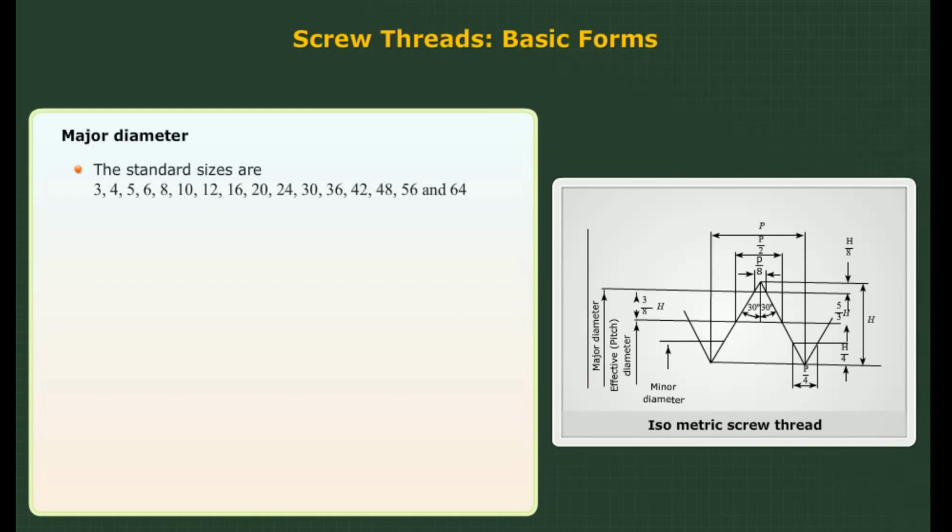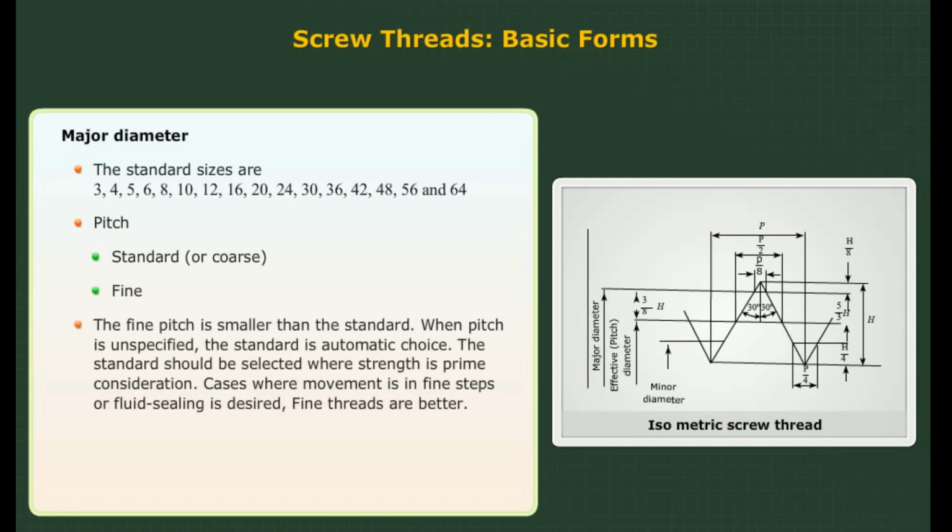Major diameter. The standard sizes are 3, 4, 5, 6, 8, 10, 12, 16, 20, 24, 30, 36, 42, 48, 56, and 64. Pitch. 1. Standard or coarse, and 2. Fine. The fine pitch is smaller than the standard. When pitch is unspecified, the standard is automatic choice.